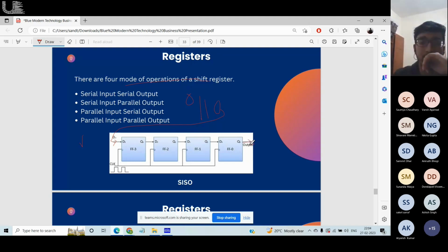So, let initially the flip-flops be 0, this also be 0, this be 0, this also be 0. Okay. So the first input is 0, right? In the first clock cycle, I'm putting in 0. And my output is 0, right? This is my output, the value at this register. The next cycle, I'm putting in 1, right? So my 1 enters in this way.